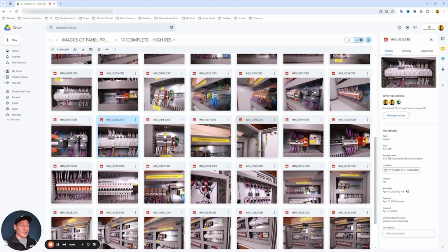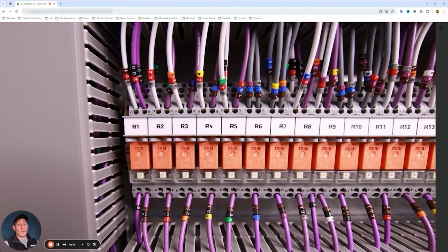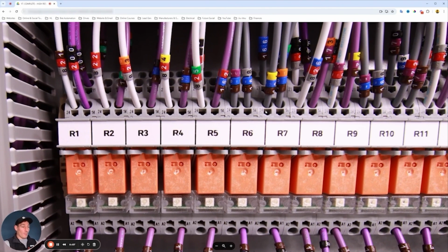Before you do that though, let's just quickly run through some images referencing the PLC side of that control. So first of all, we've switched the cam switch to auto, and then that sent 24 volts to this cable here, energizing R7 on A1. So the coil side. So that's now energized. And then we've got pole 1 and we've got pole 2, and they're in the normally open configuration. So that's energized. Now both of those contacts are closed.